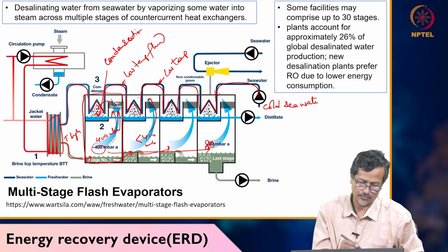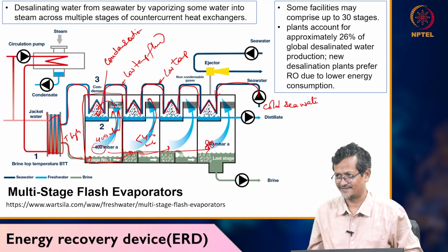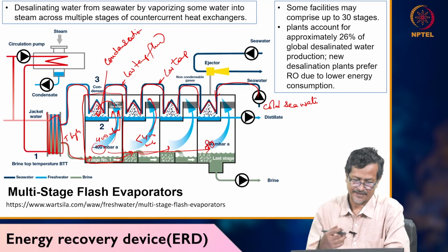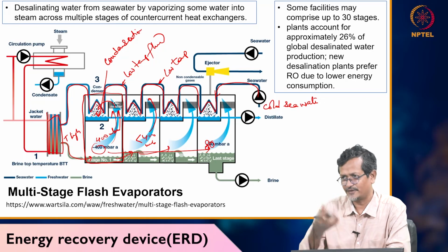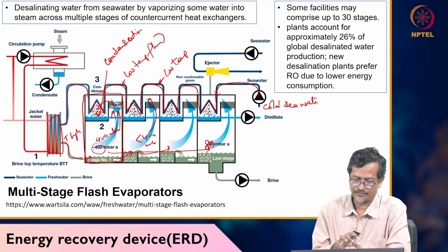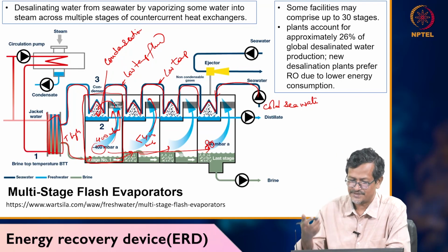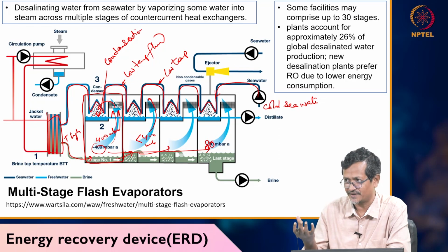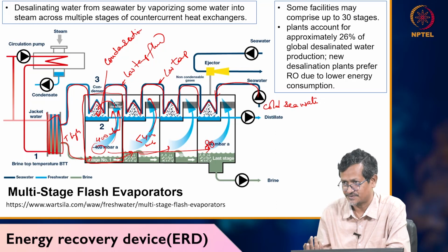So, the condensed water you collect, that is your potable water. Indirectly you are evaporating and cooling, like if you boil water, you get steam directly and then cooling, but here instead of boiling, you are reducing pressure using seabed cold temperature. Seabed temperature will be around 4 degrees. So, that temperature you are using and you are making a flash evaporation system.